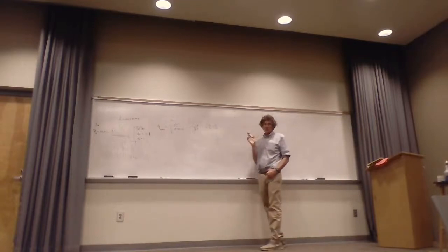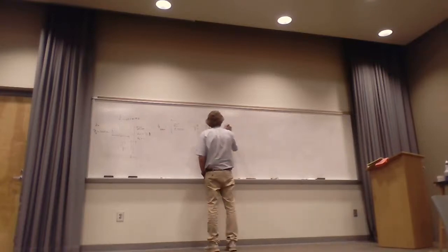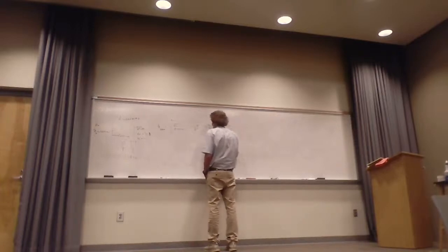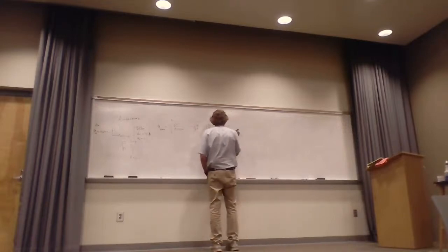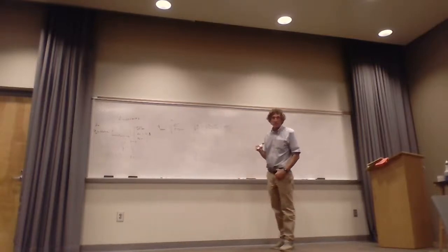There's nothing tricky here. The square root of mu naught over epsilon naught is 120 pi, or eta naught. And the square root of mu relative over epsilon relative, with mu relative 1 and epsilon relative 2.1, makes this divided by the square root of 2.1. Correct, class? And I'm just leaving it like that.